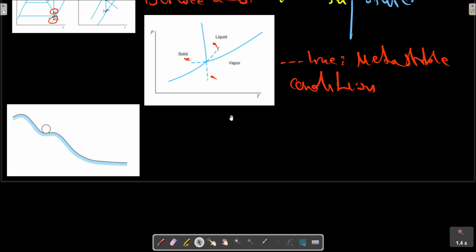The ball is in a stable position for small displacement, but with a large displacement it moves to a new equilibrium position. The steam expands in the nozzle in a metastable state between A and B. This means that droplets smaller than a certain critical size will evaporate, and only when droplets larger than this critical size have formed, which corresponds to moving the ball out of the depression, will the new equilibrium state appear. Chemical equilibrium is the next section.